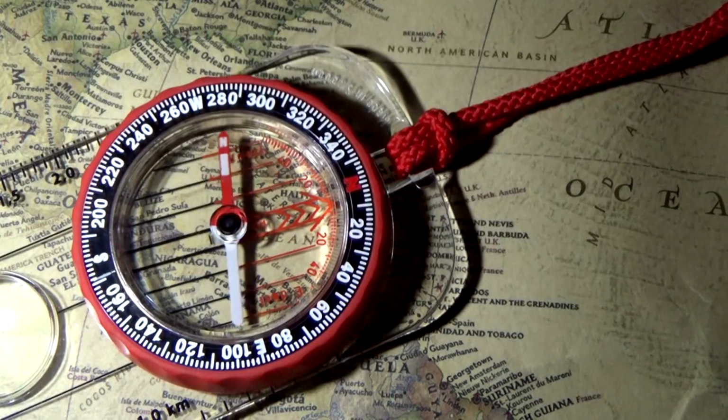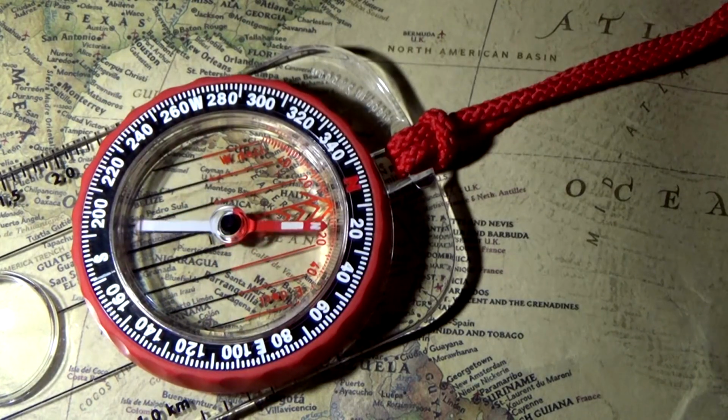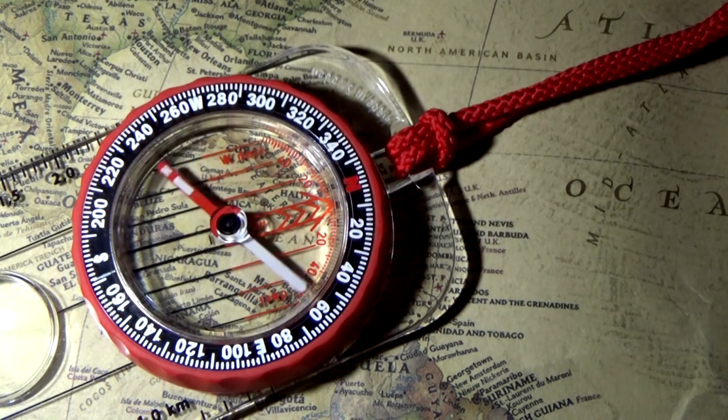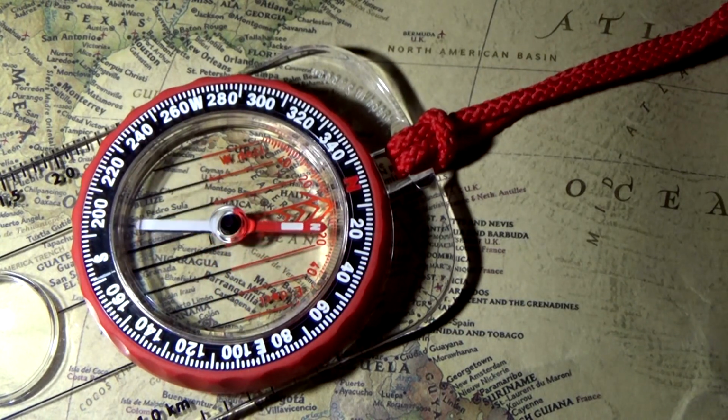Taking compass bearings. Whatever type of compass you use for taking a compass bearing, be it the steering compass, compass binoculars, or a hand-bearing compass, you must convert the compass bearing to a true bearing before plotting it on a chart, i.e. apply variation for the location you are in.